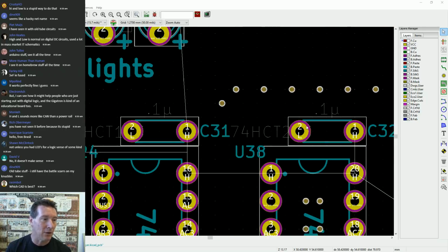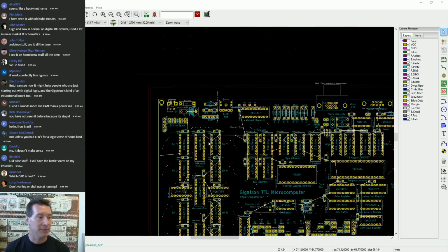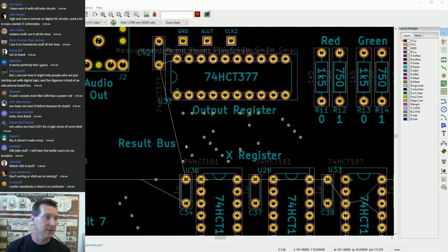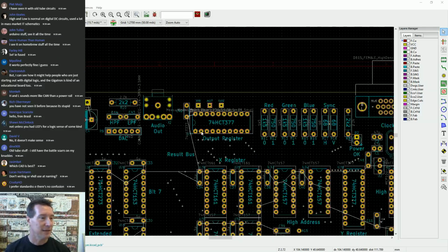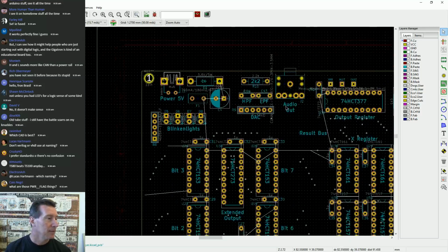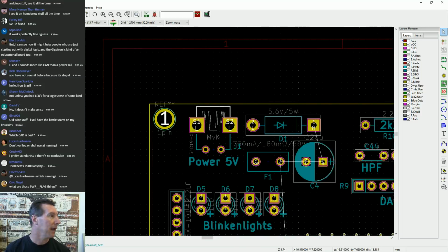We've already done L, because the only nets we're missing, based on these white net lines, they tell us that they're unrouted nets. That's the term I was looking for. They're the unrouted nets. And I guess KiCad by default has unrouted nets on, which is great. So, I've explained pullback. So, let's go in and let's place our zone again.